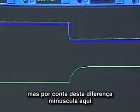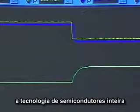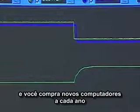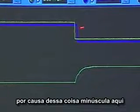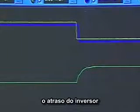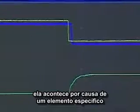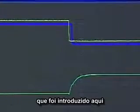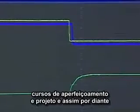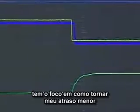But because there's this little itty-bitty difference here, our entire semiconductor technology is charging along, trying to do something about that. You buy newer and newer computers each year. It turns out this little itty-bitty thing here is called the delay, the inverter delay. Okay? And it happens because of a specific element that has been introduced here that we haven't shown you so far. And a large part of our semiconductor industry and follow-on courses and design and so on focuses on how can I make my delay smaller?